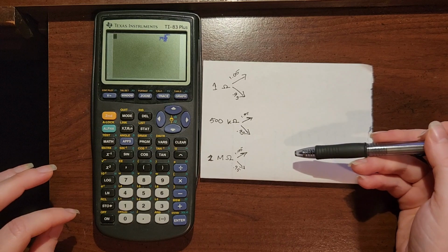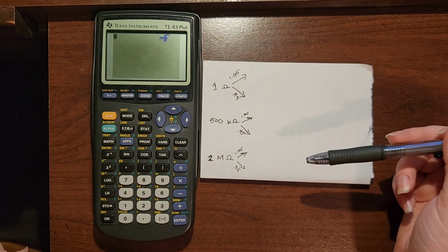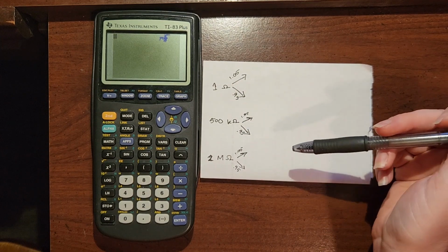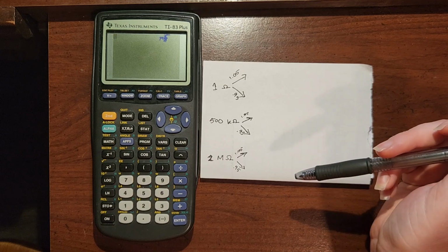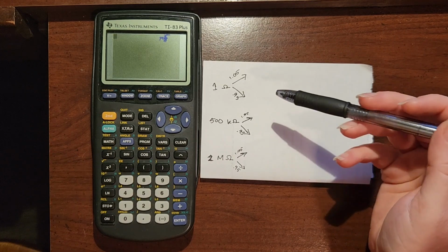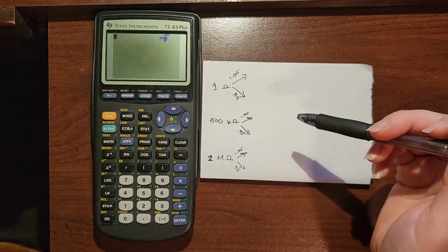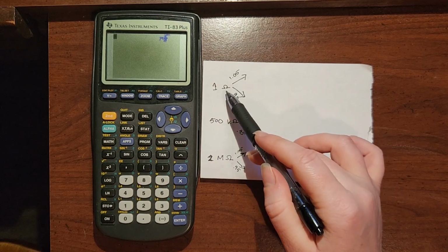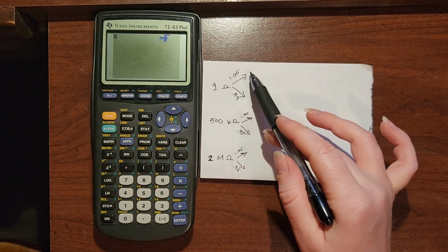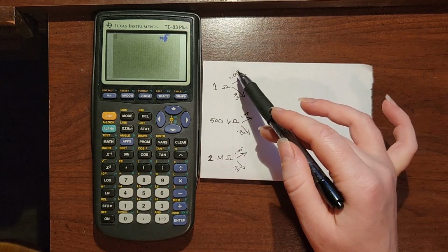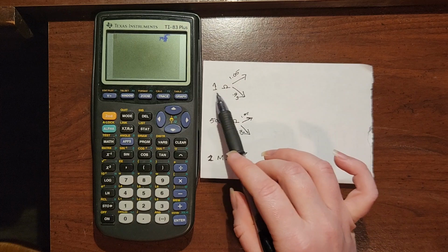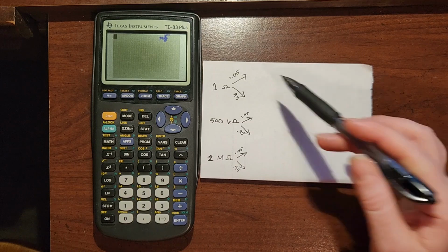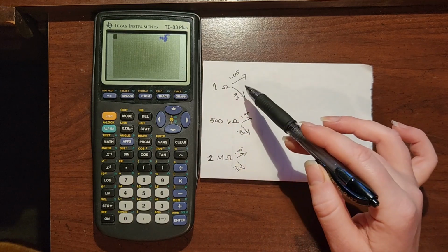And so what I've got over here are some problems in calculating tolerance for resistors. We've got a 1 ohm resistor, 500 kilo ohm, and 2 mega ohm. And we're going to just assume that they have a gold band on them that would indicate that they've got a tolerance range of 5%. And so how we calculate those is that we generally do the nominal value times 1.05, so 5% over 100% of itself, or it times 0.95, which would be 5% less than 100% of the nominal value.